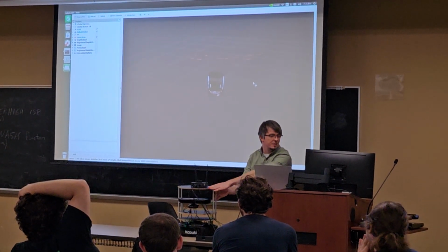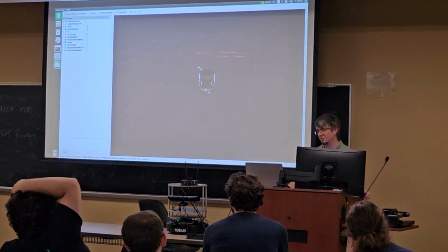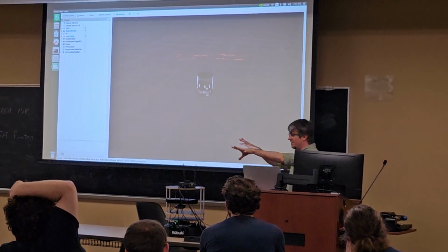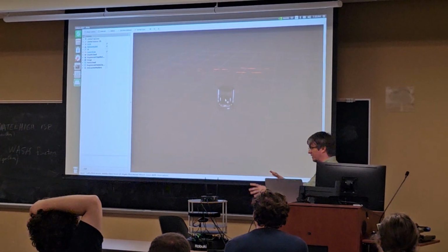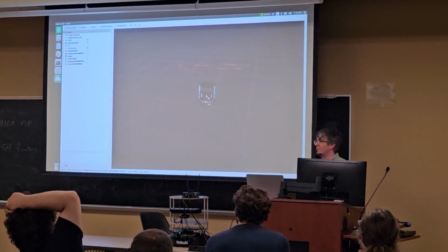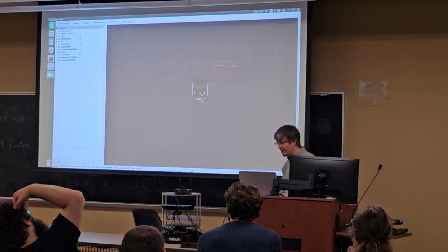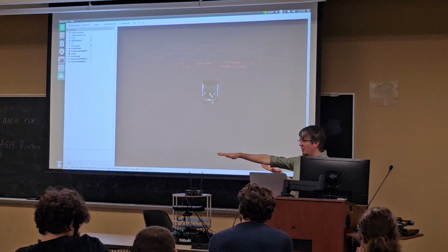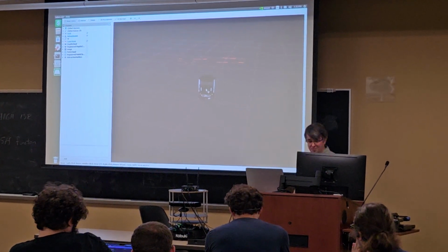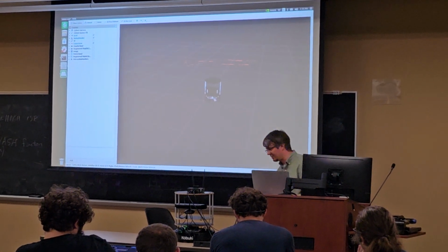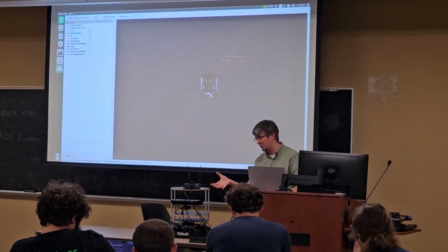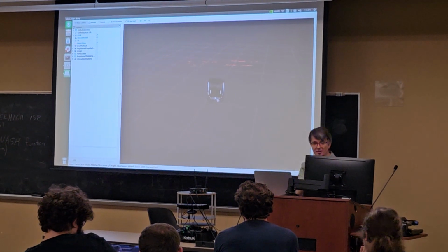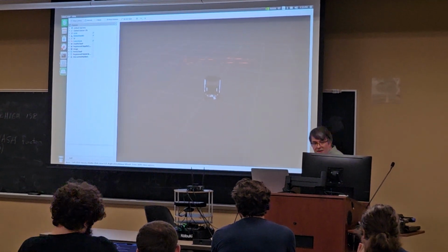So what we're looking at here is the depth camera, like I said, produces this field of infrared dots that it then tries to read the depth from. A lot of robots want to use LiDAR data for different algorithms, so that's typically a linear scan of data in front of it. And so what we're doing is this thing is spoofing the output of a LiDAR by taking that depth map and just looking at a little slice of it. And that's what we're looking at right here.